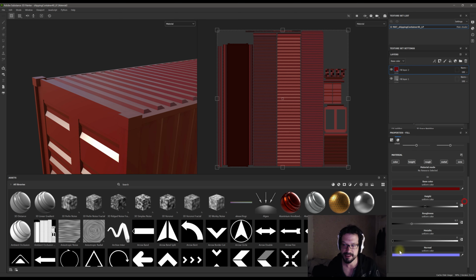And since this paint is dielectric in nature, I mean, it is probably an epoxy-based paint, it is plasticky in nature, it will be non-metallic, so metallicness is 0, but it will also be somewhat glossy. I'm going to go with 0.2.